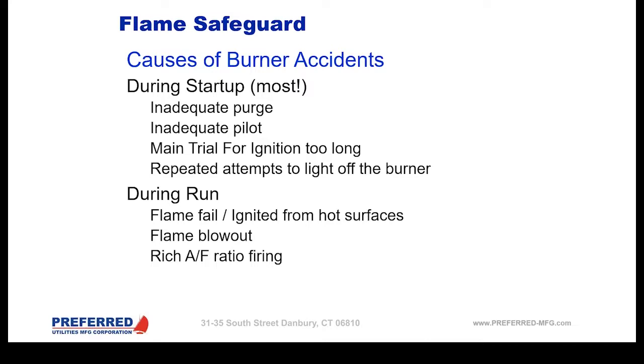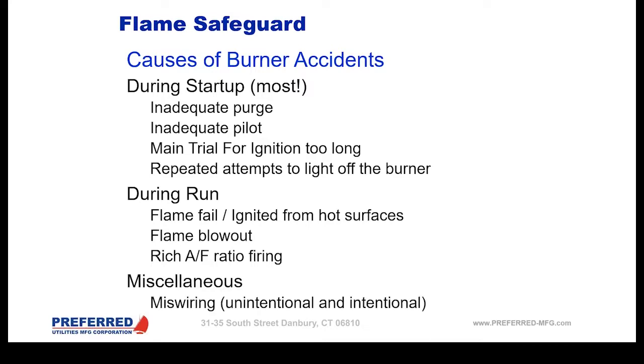This is also extremely dangerous, particularly in the winter months when a lot of operators will tend to start closing the air inlets into a boiler room, for instance, and quite honestly, the burner will then start firing rich. And if someone then opens doors or something happens where it gets a burst of fresh air, you could actually have a mild explosion, you could have a bad explosion. So that is extremely important that the air-fuel ratio is monitored properly.